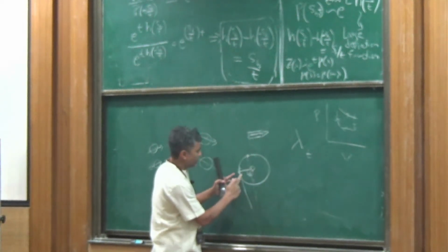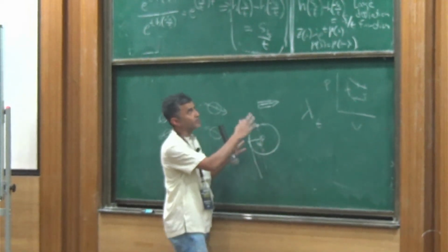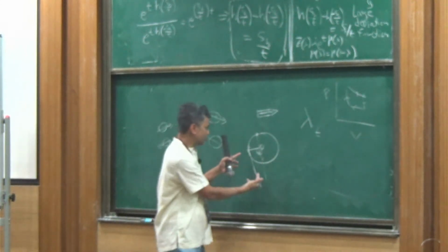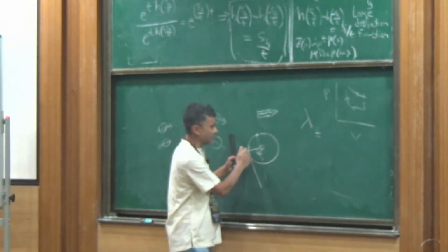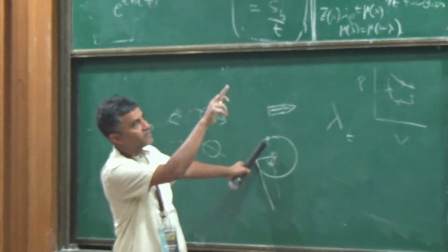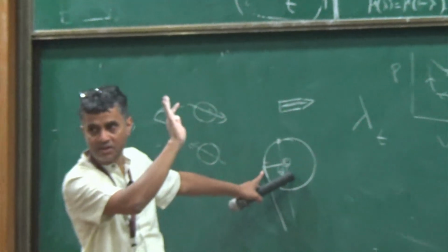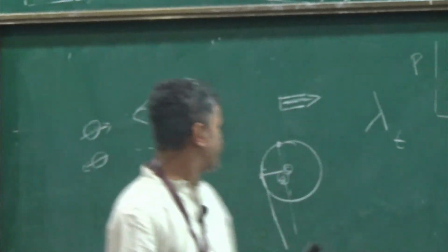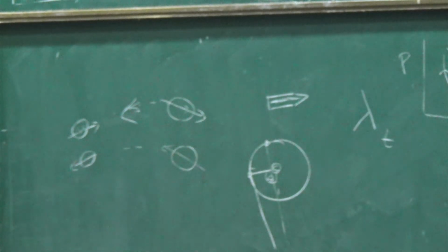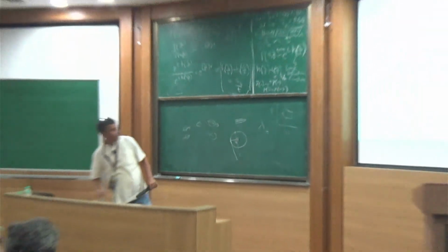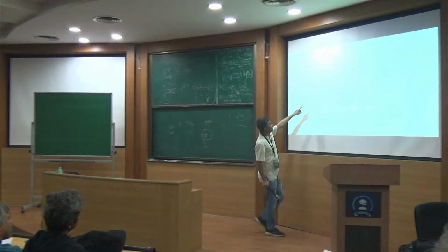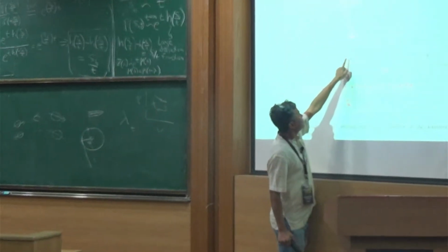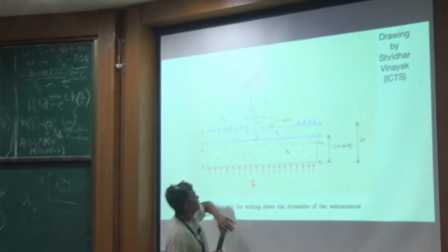Now I'm just writing an equation for this wheel. I is the moment of inertia around this axis. So I theta double dot equals the torque from these, that is F sine theta, and then there's just friction. Now, where does F sine theta come from? It's basically the force on this piston, the red one. There's another piston.